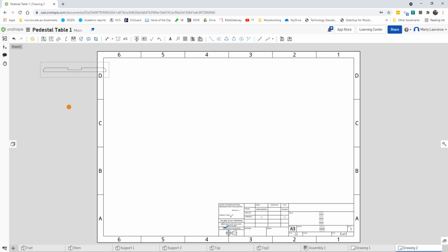Whoops, what did I do? I accidentally clicked there and it placed that view right there. And see what it did straight away? It jumped to the projected view. So that's what this weird box that's following my cursor around is. So I'm actually just going to cancel out of that by clicking that again. So nothing is selected and I can drag my item back into the page.